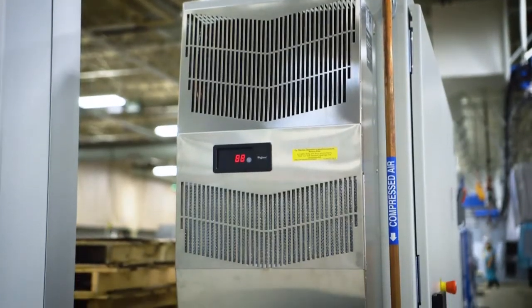Our ambient temperature plays a large part in choosing a cooling option, whether or not we can have open loop, closed loop, or conductive cooling. Open loop solution will always have our temperature above the ambient temperature. This is something that people need to pay attention to.